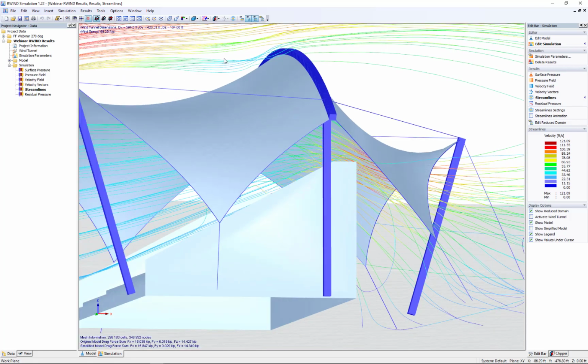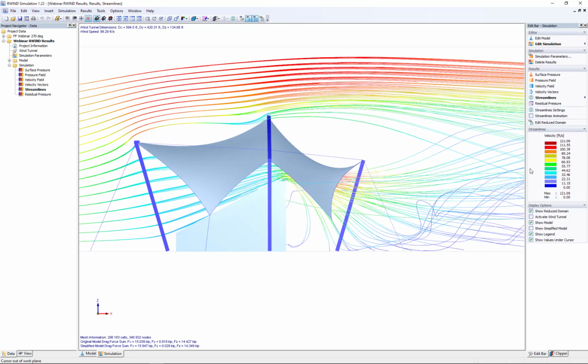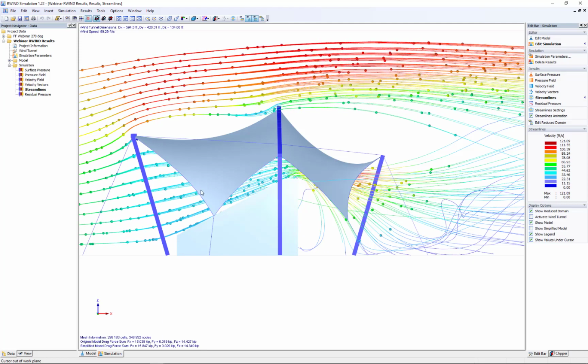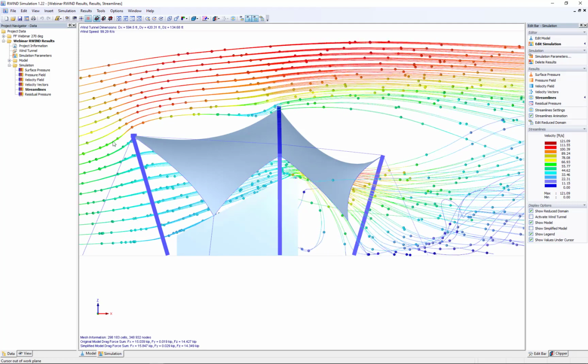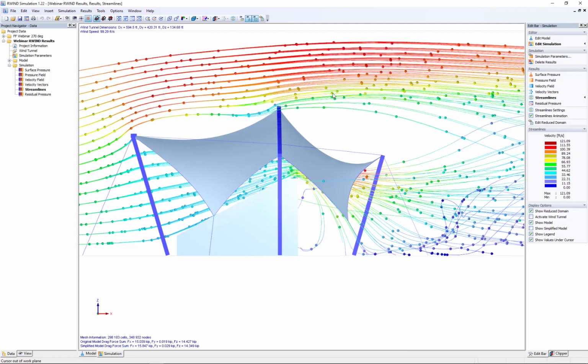And we can turn this back into the Y direction. What also is powerful is let's turn on our streamline animation. So for this, I've set this to particles to follow those streamlines, and you can see them hitting this stair structure and then passing out through the top. Now, additionally, we have the wind, of course, just passing through the top here as well.